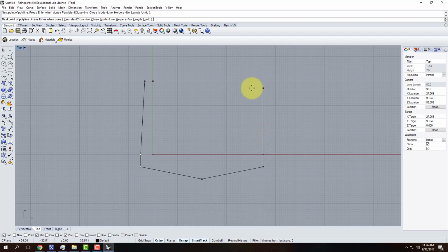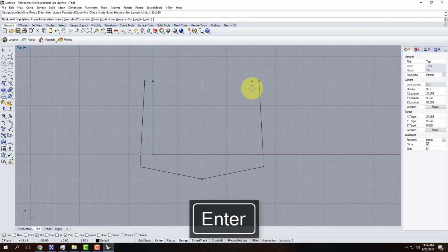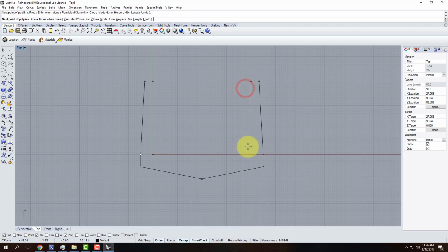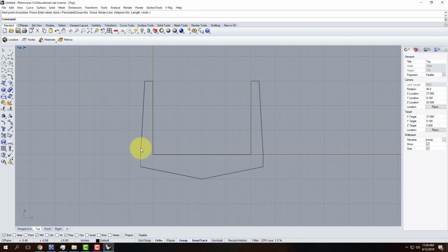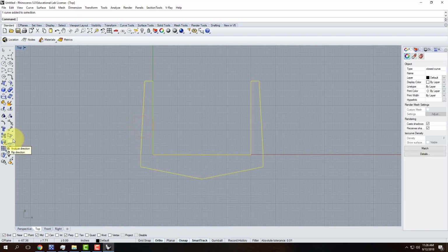Then this one would be, again, the at sign, -2 in the x, followed by 36 in the y. It's +36 again. So at -2, 36. And then we can go over the 4. We can go down the 36. And then we can come back to where we started from. And that ultimately creates this shape, which is the shape I'm asking you to create here on your drawing as well.